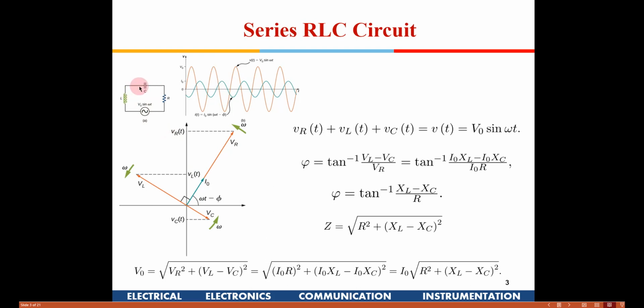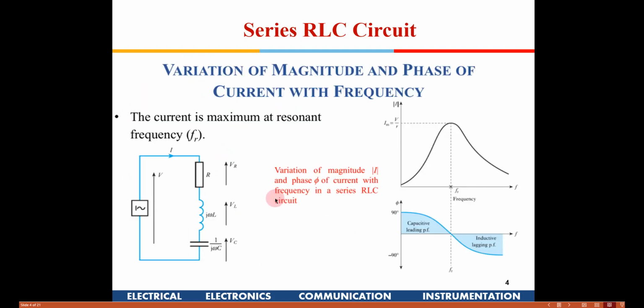When I discussed the inductor, we saw that a spark could fly between the terminals of the relay. The same thing can happen in these kinds of circuits also. The voltages across the inductor and capacitor can go much higher for certain frequencies and certain values of L and C, so you need to be careful with that aspect.